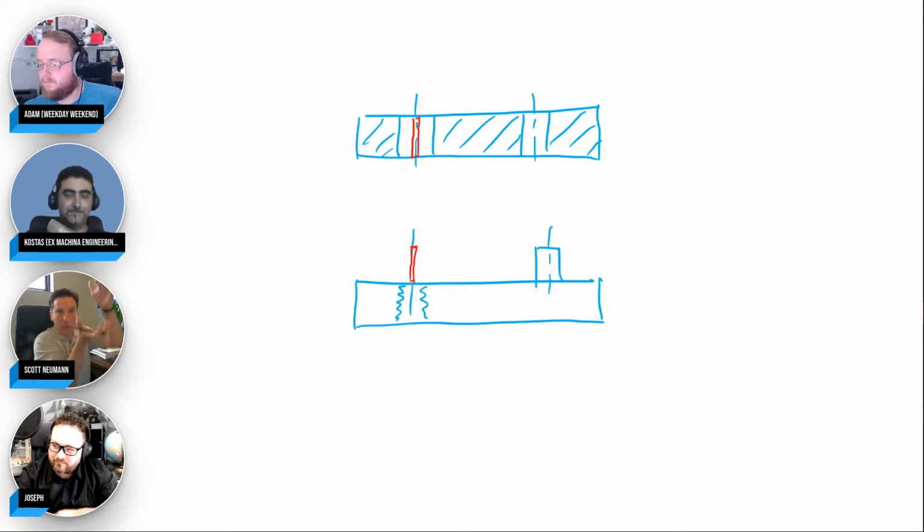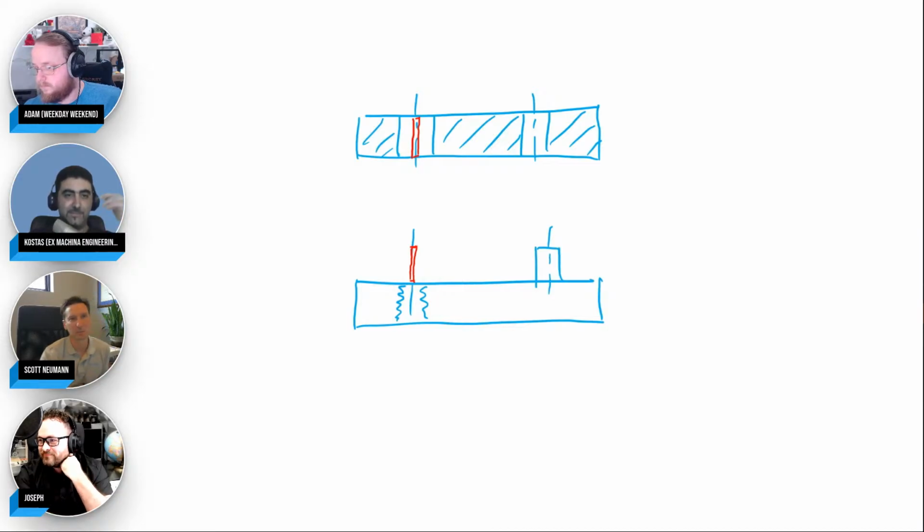And that way, when I put these two parts and mate them in the CAD, then the tolerance zone will overlap with the tolerance zone, and you're back to a really easy smallest hole, biggest pin calculation. So it's like you're ghosting in a part that's not there and then tolerancing it, because that's what matters. It's the part that's going to do the work. I'm just like, man, that's so clever.